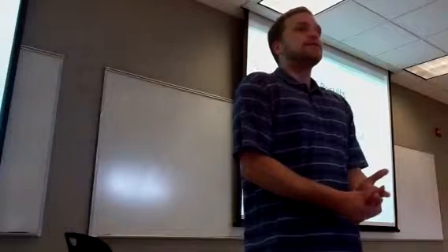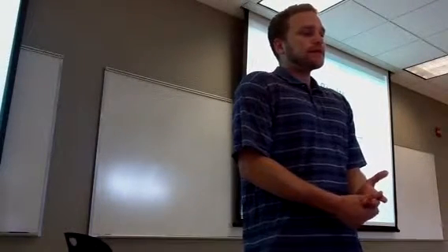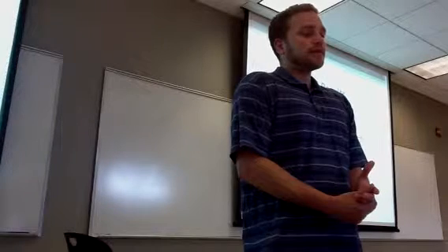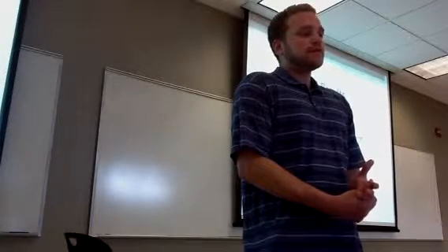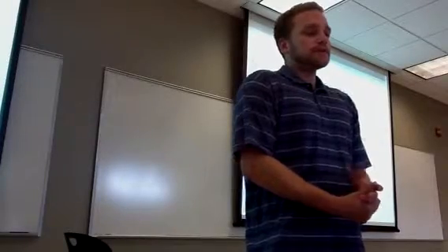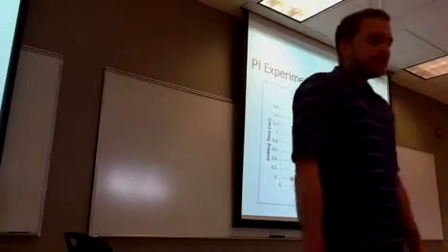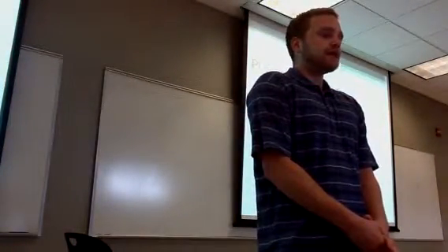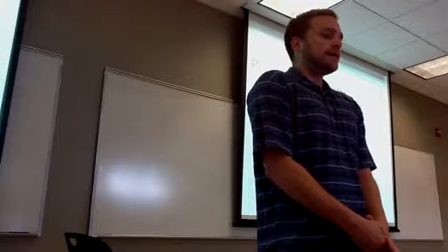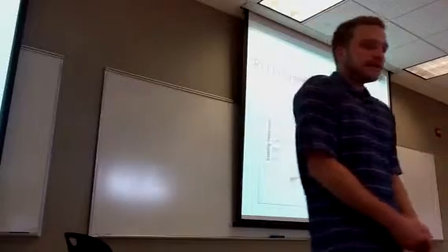And here's a plot of the decay ratios for the 35 to 65% range. The TI of 0.08 is constantly oscillatory, that's why it's a straight line at 1. And then the TI of 0.24 and TI of 0.72 both behave very similarly, as I said before. The settling time, they also behave pretty similarly. They're on top of each other at the beginning, so you can't see it. And then over at 0.12, they deviate from each other.